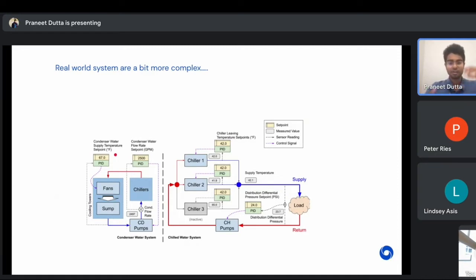Chillers are rated for a certain amount of, the term is tonnage. So they are rated to provide a certain amount of cooling in terms of this quantity. So if it's a small building, you might just go with one small chiller, versus a large industrial facility, where you need multiple of these in parallel. Think of it like batteries: a fully electric car requires a lot more batteries versus a handheld remote, which requires a smaller AAA battery, right? So different building topologies dictate different architectures, but they overall consist of the same fundamental units.